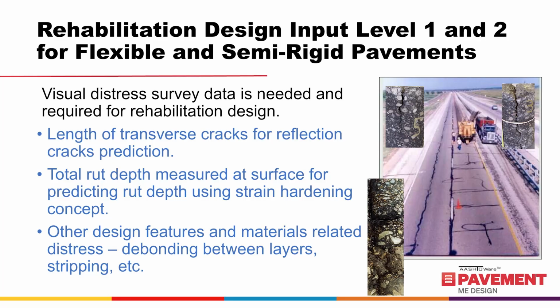Any deflection measurements to estimate the load transfer efficiency, which is LTE, of the transverse cracks, should be separated from the measurements of areas without fatigue cracks and in areas with fatigue cracks. Deflection tests to estimate the load transfer efficiency will be discussed later in this session.